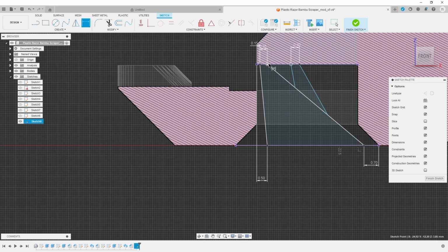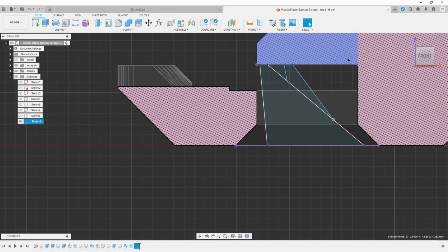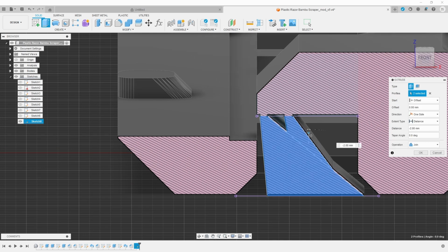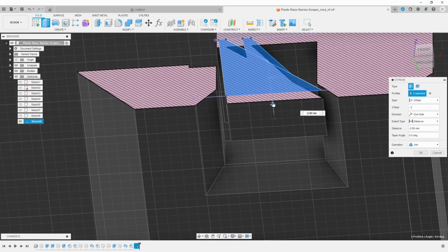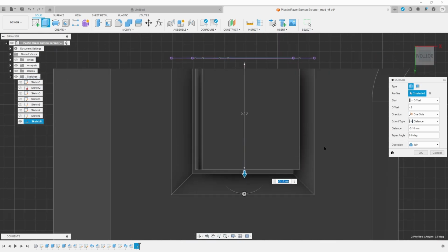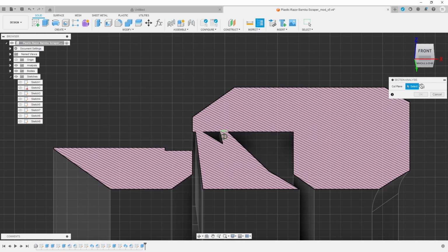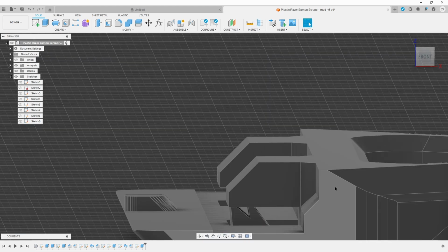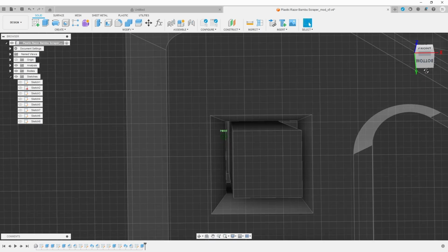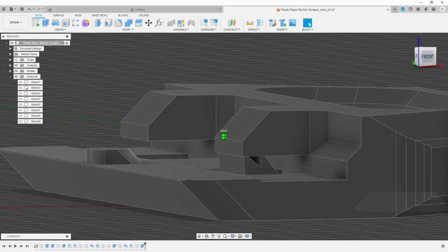I want it very narrow, and I just want a single extrusion to be connected to those other pieces. I've not just placed the very end, but I also have a support partway through, and then I'm adjusting the extrusion offset as needed so that I can get the width of it without any chance of it touching the walls. I don't want it to actually contact the wall of my feature. So I need to remove the cut plane to make sure that it's not in the way, and carefully examine it to make sure that I'm not touching the wall, which we're not. So that's very good.